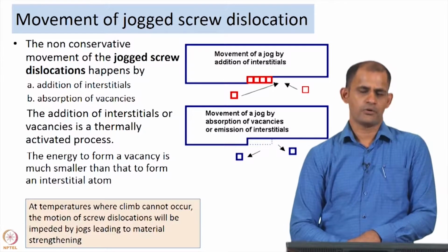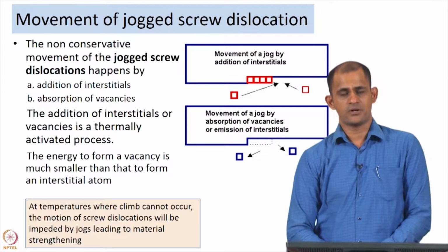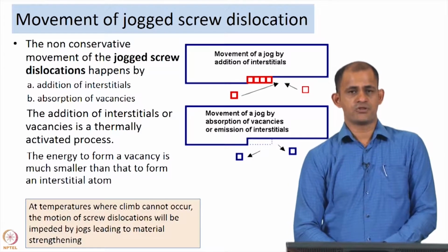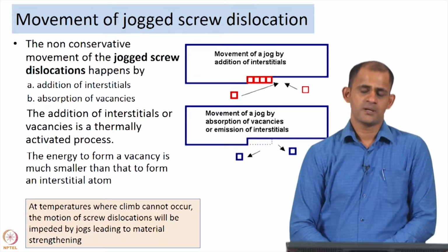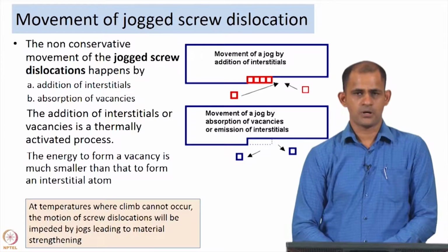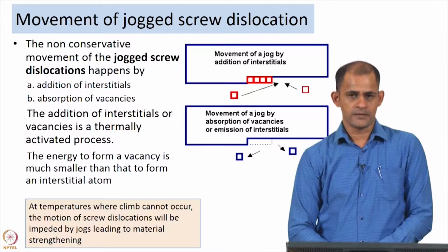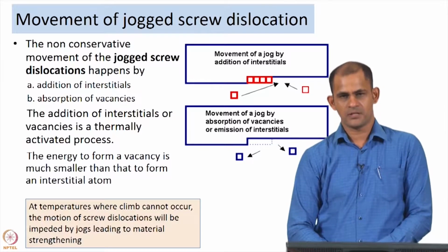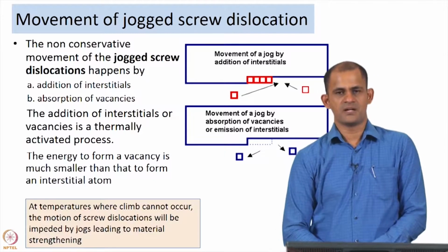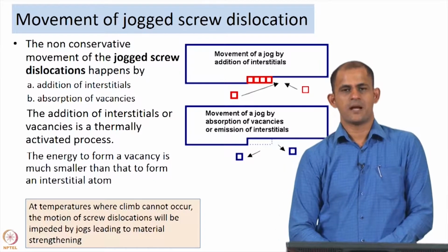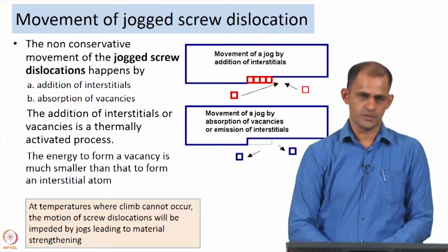dislocations. So, we are going to talk about the kind of forces that exist between dislocations, the energy of a dislocation, and the strain rate of deformation produced by the motion of a dislocation and things like that. Again this is all important because it will help us in gathering understanding in depth of creep behavior of a material, because like I mentioned in the beginning, creep behavior involves the motion of defects, and dislocation is an important defect that contributes towards plastic deformation or creep deformation.